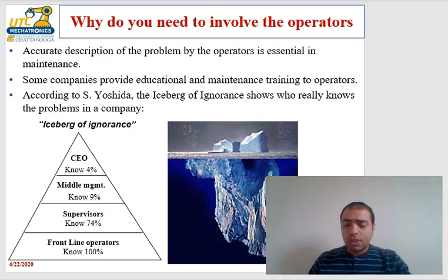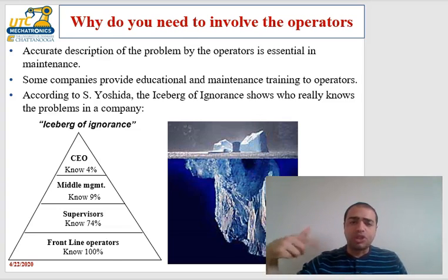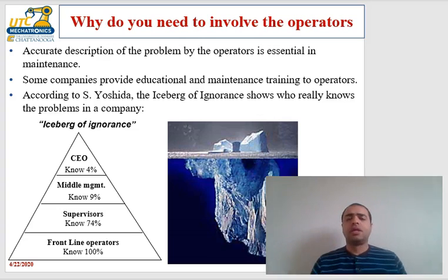When technicians see an overload trip, they will try to oversize the overload relay. They'll think it's undersized, or they will replace a part that went bad, but it keeps tripping, when the problem is actually the bearings. If they communicate with the operator, they will know, for example, that the operator hears a friction sound. So the operator actually knows the problem. That's why a lot of companies, like Siemens, introduced a program to train the operators on simple maintenance. It's extremely effective, because they can pinpoint the problem for you.